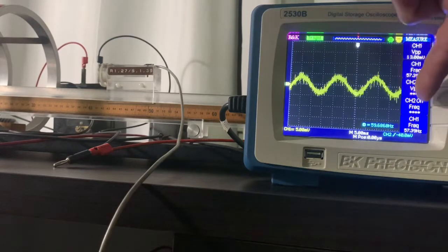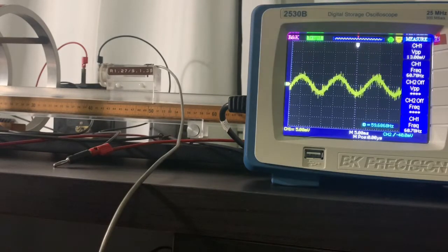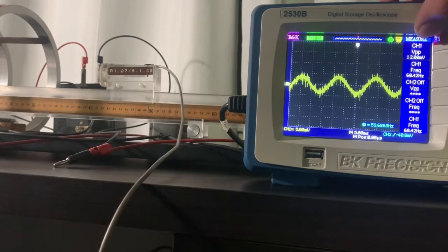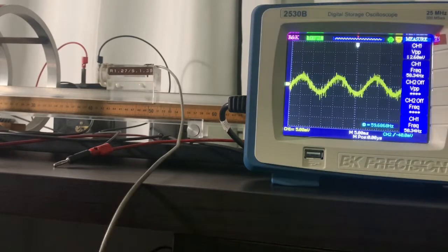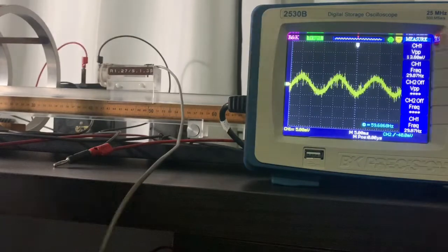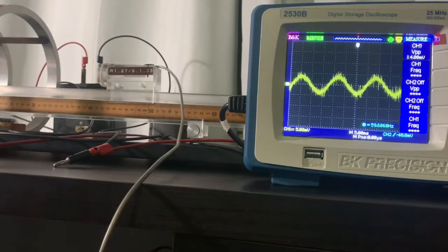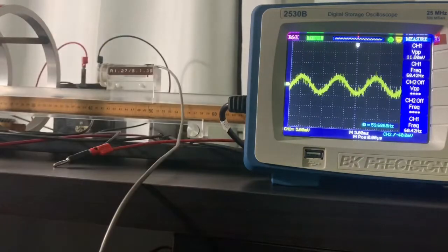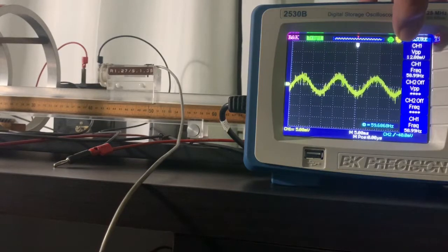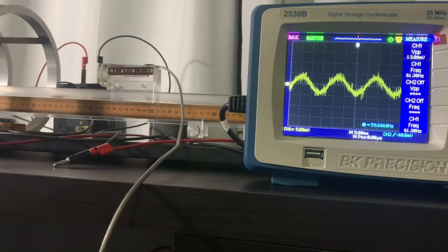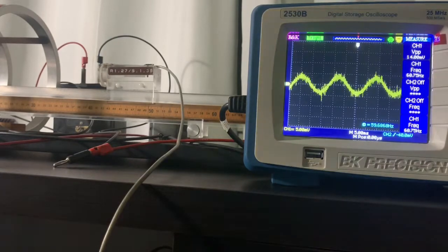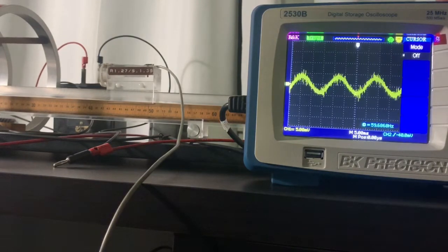I preset these displays to the measurements of interest. For instance, channel 1, the voltage peak to peak, channel 1, frequency, channel 1, search coil. And like I was saying, notice there's a bunch of noise in that curve. So if I look at this peak to peak voltage, it really isn't 12.4 millivolts. That isn't a good representation of what that peak to peak is. In fact, let's prove it.